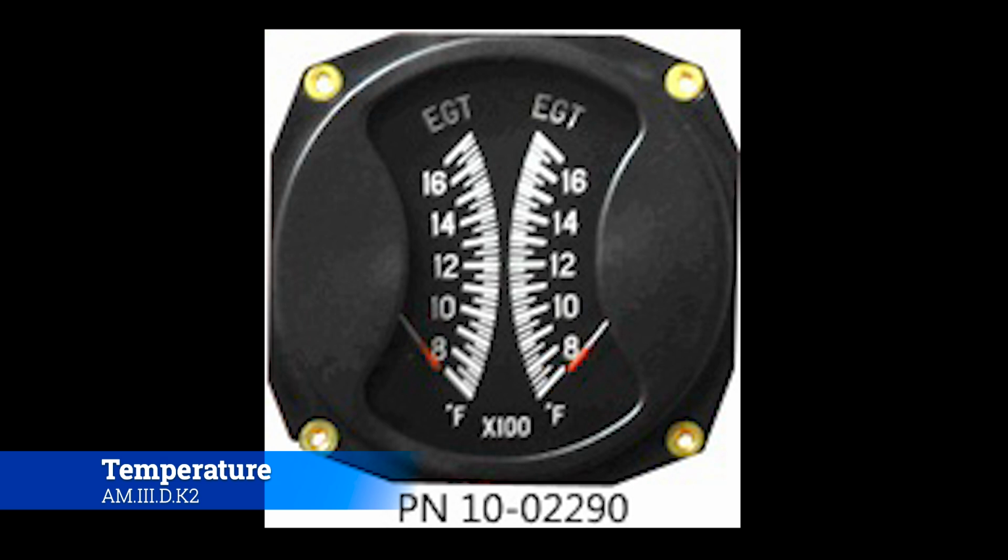However, that being said, it has become a kind of staple with a lot of reciprocating engine health metrics, especially as more and more digital displays start to get worked into the mix. It's very easy to detect EGT. It's simply a probe into the exhaust. As the exhaust goes by, it'll tell you, hey, this is what the EGT is here. Now that tells us a lot of things. It tells us basically what the interior health of that cylinder looks like.